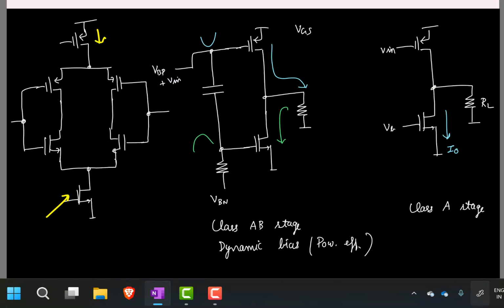So which means the signals are no longer small signals. If I have a large VGS and if my signal is varying, it is small. But here it is already a small VGS. On top of it, you have the input signal applied. So my small signal linear approximation will not be really valid. So this will act more non-linearly.